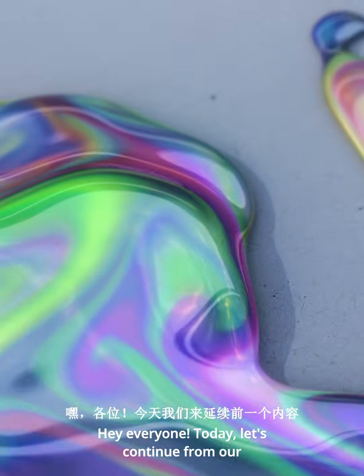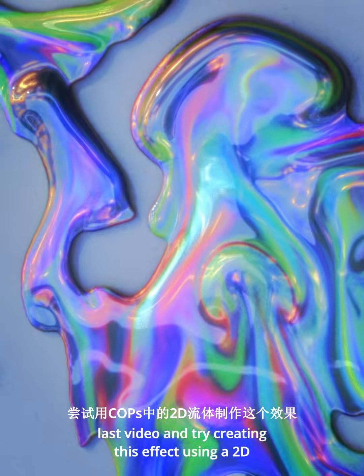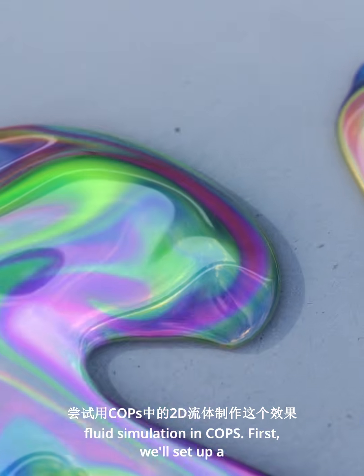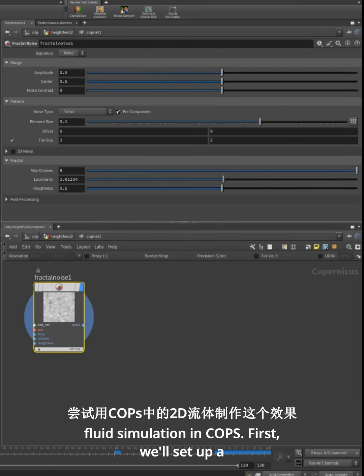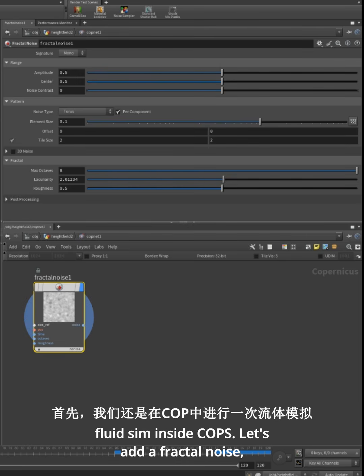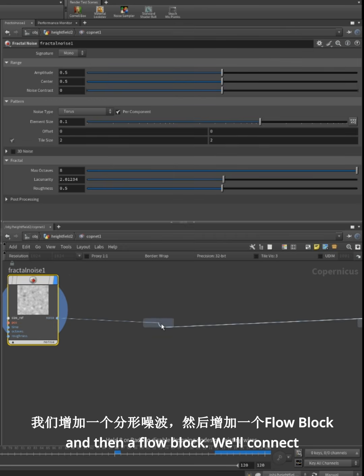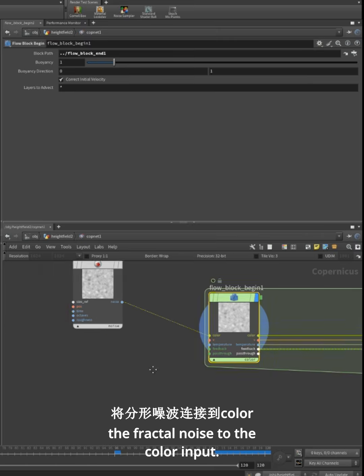Hey everyone! Today, let's continue from our last video and try creating this effect using a 2D fluid simulation in COPS. First, we'll set up a fluid sim inside COPS. Let's add a fractal noise and then a flow block. We'll connect the fractal noise to the color input.